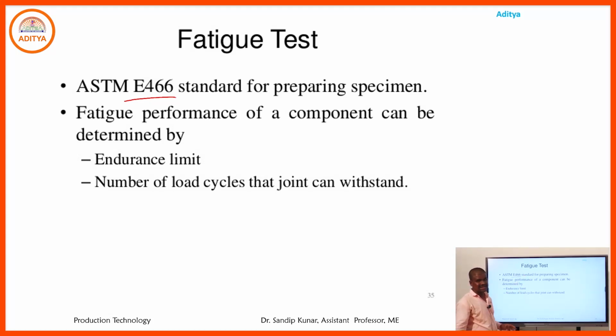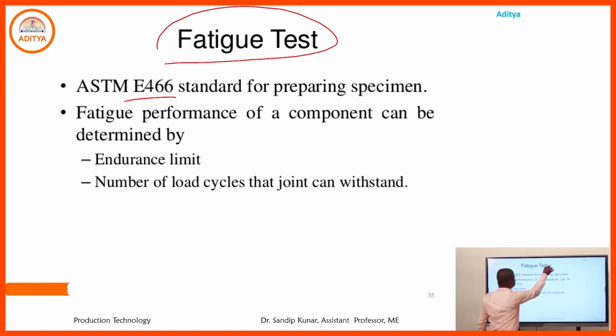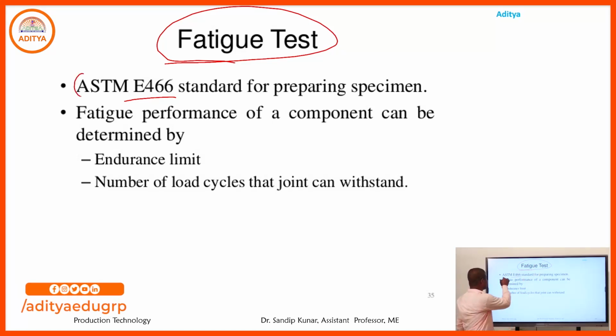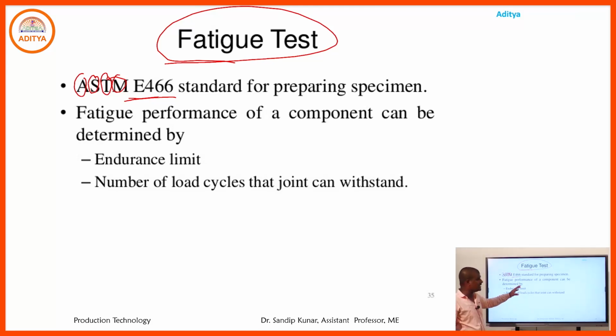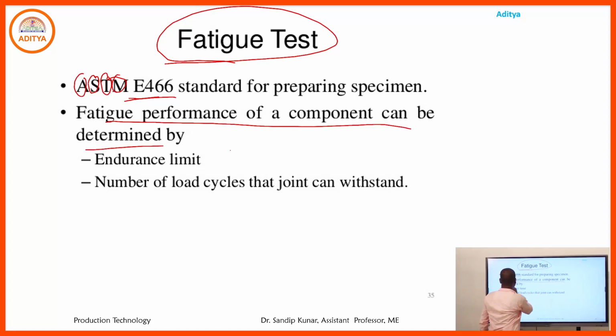So in that case, for the fatigue test we are taking one standard specimen, American Society for Testing and Materials E466. Fatigue performance of a component can be determined by the endurance limit, meaning up to that limit the material can sustain. We are welding that particular specimen, and using that weld component we are doing the fatigue test.